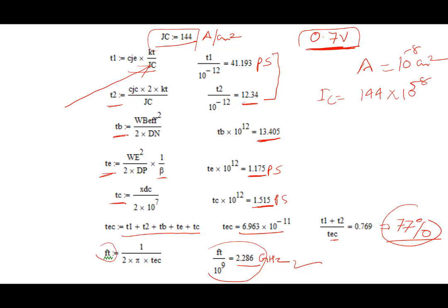Right, so this is equal to 0.014, something like milliampere, right? I think 0.014 milliamp. So, increase the current density, increase the collector current, bias your transistor at higher current. If you bias it at higher current, these delays should come down, right? So if I simply increase the current by a factor of 10, this should become 4 picosecond.